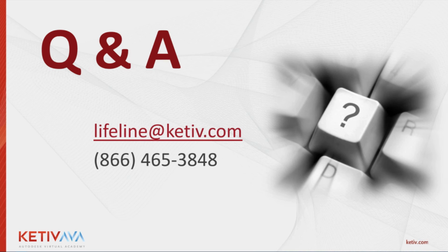Well, this is the chicken or the egg type of question. It's always better to work locally. So Vault would be a benefit for you because you would be able to just get your files locally and update as soon as the update happens. But through a network, it could lag, especially during lunchtime where everybody's on the internet and trying to update Facebook and all this. You can experience some lagging. So working locally is actually the key to this success as much as possible. And Vault will be a great benefit for that.